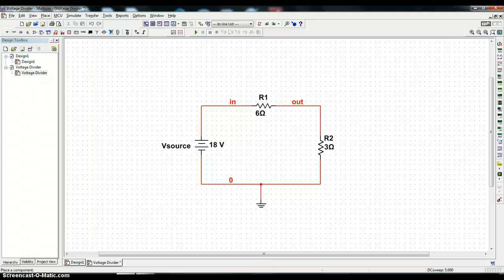The title of this tutorial is DC sweep analysis. We will employ the same simple voltage divider circuit used in a couple of other DC tutorials. With this voltage divider that we have on the screen, we are going to go to the DC sweep analysis feature. Now, as discussed in another tutorial, I will make use of the particular icon here known as grapher.